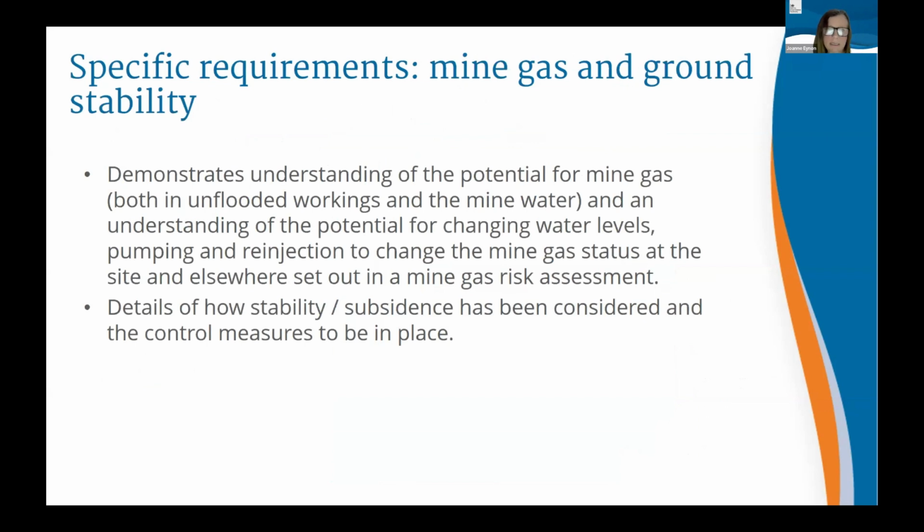Mine gas and ground stability. We want to understand the potential for mine gas, both within the unflooded workings and within the mine water, and the potential for changing water levels, pumping and re-injection to change the mine gas status at the site and elsewhere within the system. This is to be set out within a mine gas risk assessment. We also need to review details of how stability and subsidence have been considered as part of the scheme and the control measures to be put in place.